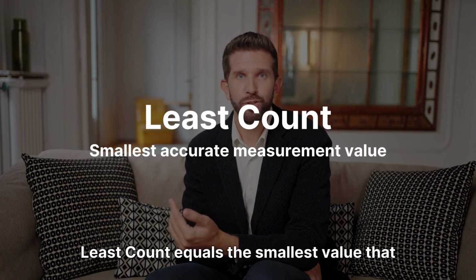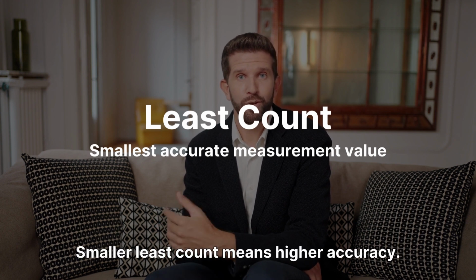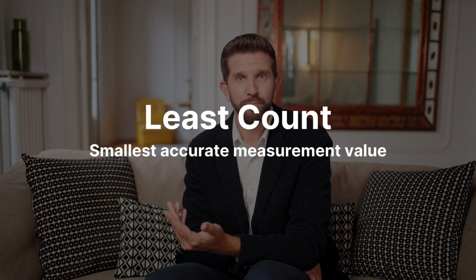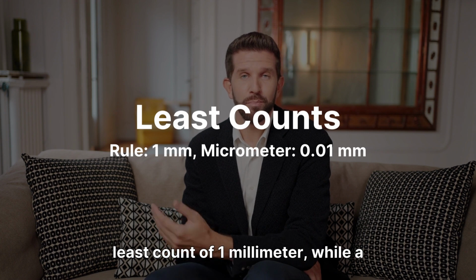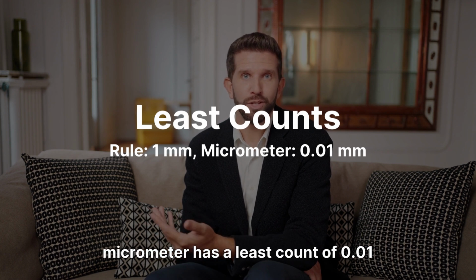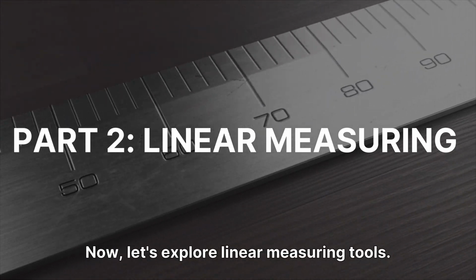Least count equals the smallest value that a measuring instrument can measure accurately. Smaller least count means higher accuracy. For example, a steel rule has a least count of 1 millimeter, while a micrometer has a least count of 0.01 millimeter. Now, let's explore linear measuring tools.